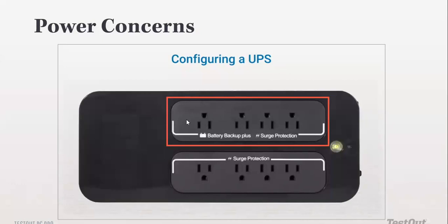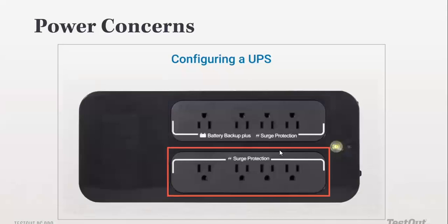All right. You see this section here, which is the part of the UPS that provides battery backup. Don't plug a laser printer here. The reason being that laser printers consume an outrageous amount of electricity. The amount of electricity that they need to function is just on a whole new level. So you have to try as much as possible to avoid using these battery backup ports to plug in laser printers. Unless it is extremely necessary, do not plug laser printers into the backup ports of your UPS.